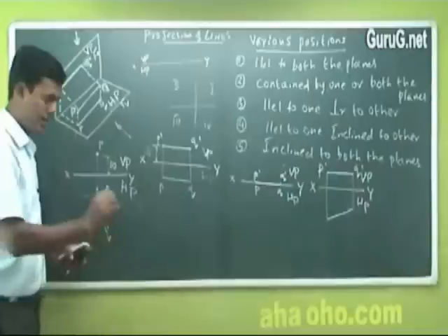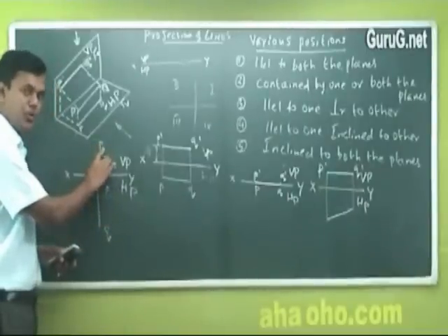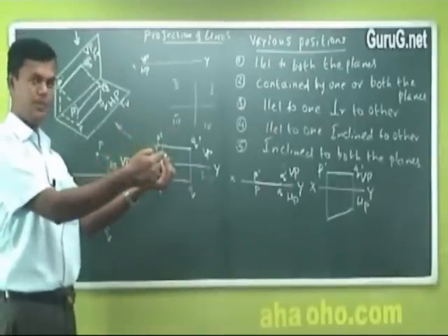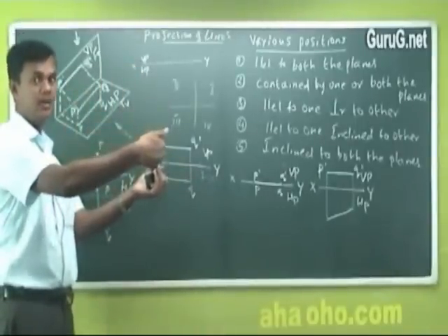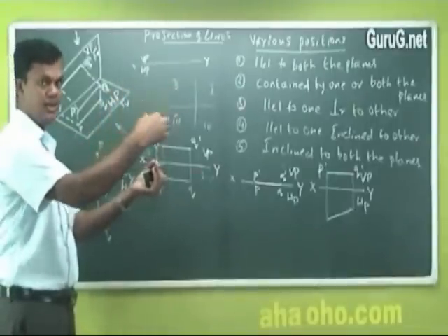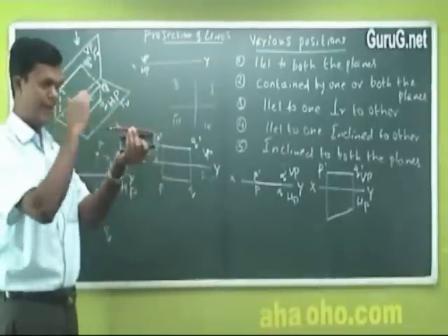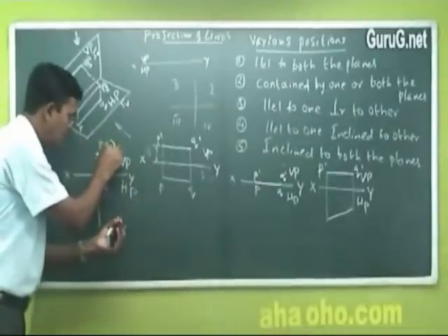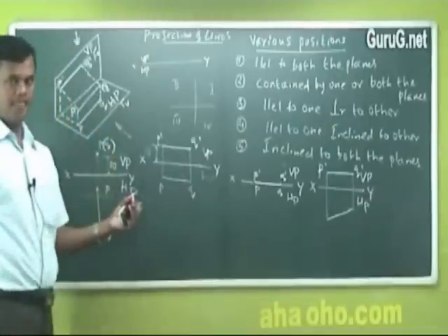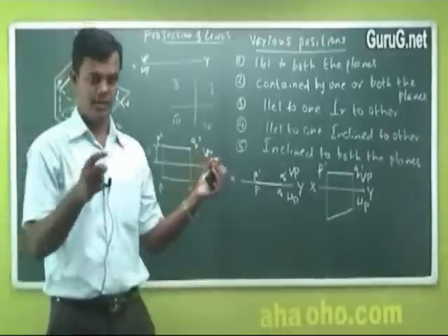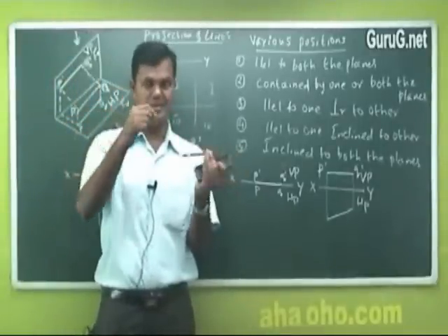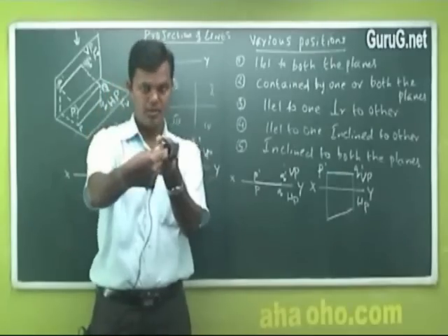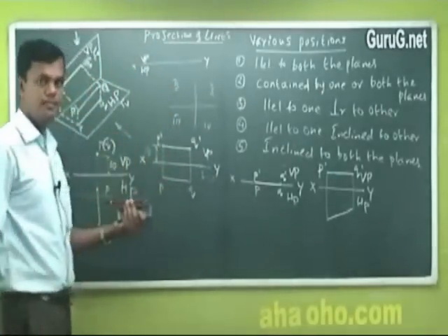Is it okay? Now this P point I have shown, but where is the Q point? P is here. I have just seen the P point. Q is actually hiding, meaning hidden. You cannot see that. It won't come into the picture. It comes on the back side of this. How will I denote it? I'll just denote it like this and put a bracket with a letter inside, which means it is not visible to the direct eye. It becomes the back side. That means it is the hidden point.